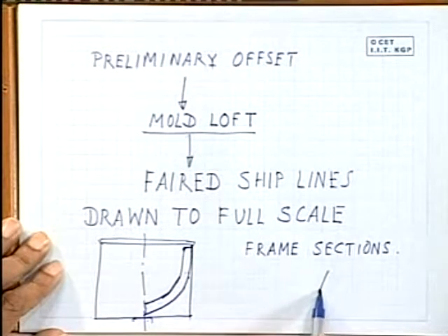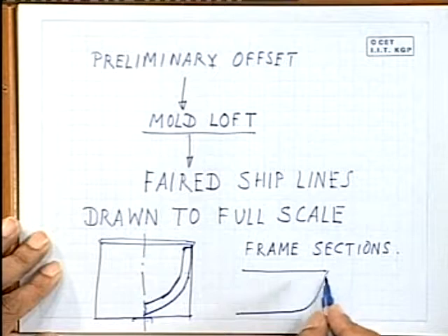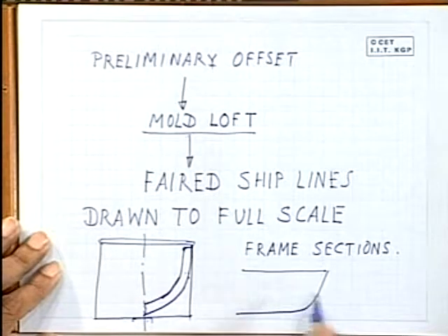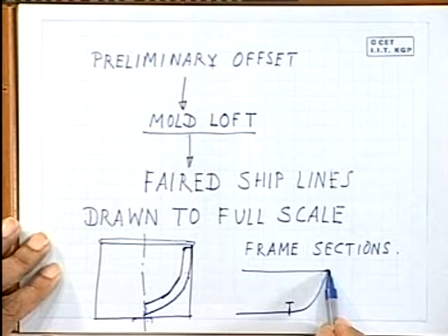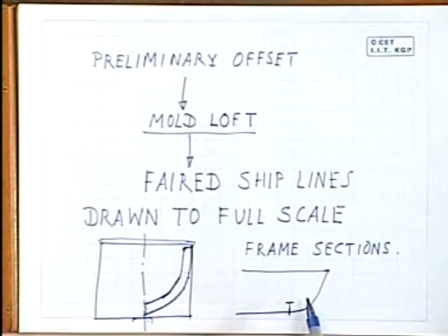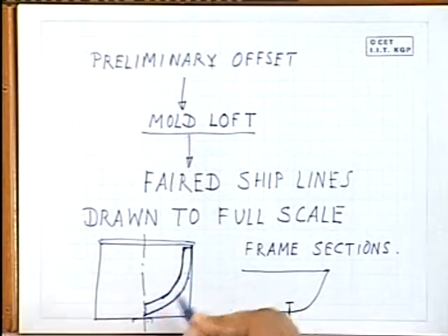Now, if you take a profile, sometimes you will find the floors. Normally, floors are not horizontal in ships, but are vertical structural members. A floor can be a T section, and how one has to position the floor is again on the molded line. For the T section, one edge has to be placed on the molded line. Every shipyard normally follows its own practice in erecting the sections on the molded line.